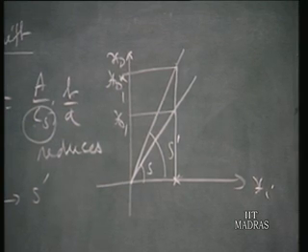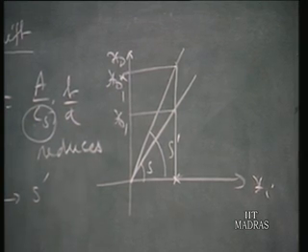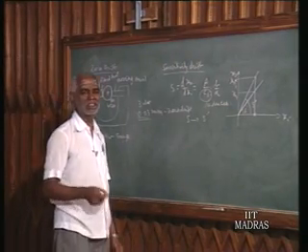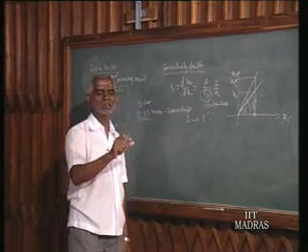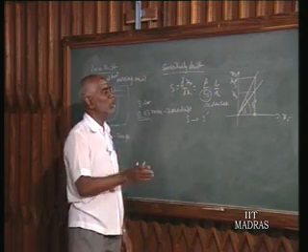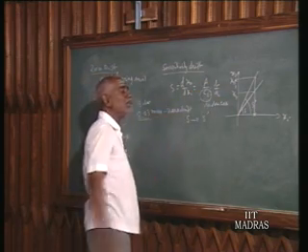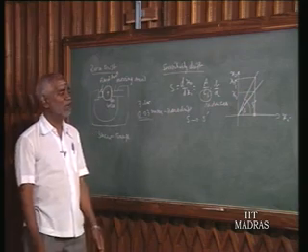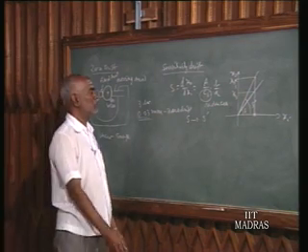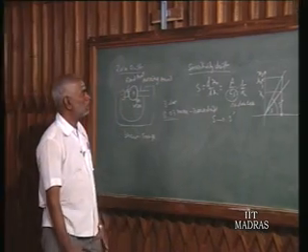We should avoid that. That's why we are supposed to use the instruments in the controlled conditions which the manufacturer mentioned. We use the instruments between plus 20 to plus 40. Beyond that range, if you use them, then the error depends upon the value of the input signal in this particular case, or it may vary in different situations. That is our sensitivity drift.